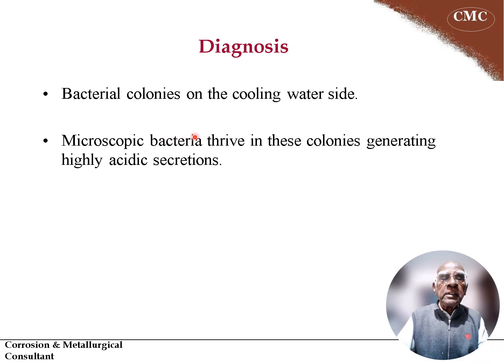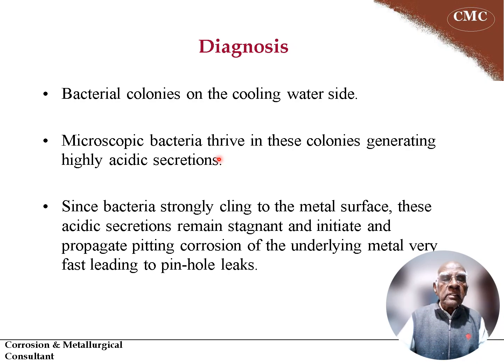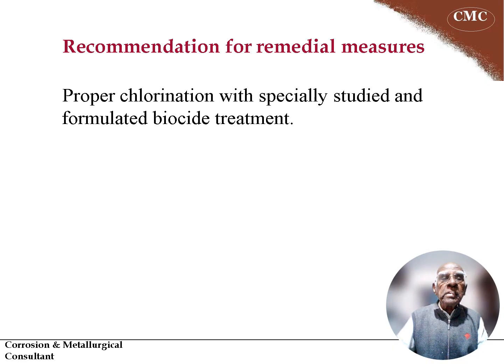So the microscopic bacteria thrive in these colonies, generating highly acidic secretions. Secretions is the word used for bacterial outlets. And since the bacteria strongly cling to the metal surface, these acidic solutions remain stagnant and initiate and propagate pitting corrosion, very localized pitting corrosion of the underlying metal, quickly leading to pinhole leaks. This is the diagnosis. The recommendation is proper chlorination with specially studied and formulated biocide treatment.